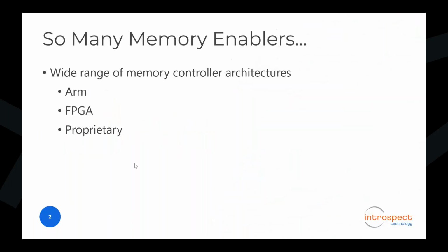So I thought of starting by just describing the memory landscape today as we see it, both in the world of DDR and LPDDR. One of the things that is very evident these days compared to decades ago is that there are so many more memory controller architectures in the world. Of course, there's the original x86 architectures, but then there's ARM that's very pervasive now, and then there are other applications like FPGA applications and proprietary applications. So more and more people are getting into the design of their own PHY and controller architectures.